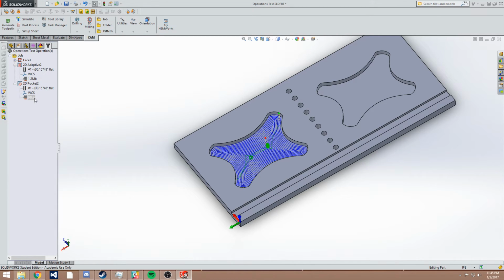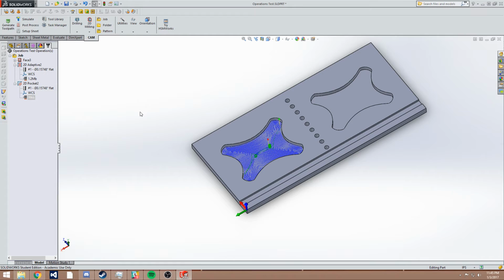So it's simpler, yes, but it also does wear a lot more on your tool. Now, since we're not a job shop and we don't need to worry about extending those tool lives as long as humanly possible, we really can use either one. It really just is a matter of preference. I personally like the adaptive for shapes like this. It might be a bit slower, but it is a lot safer, and you'll generally break a lot fewer tool bits doing it this way. But again, it's just a matter of personal opinion. If you program either one correctly, you should be fine.